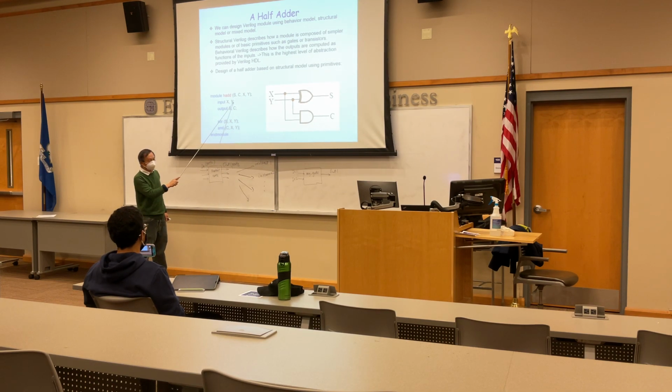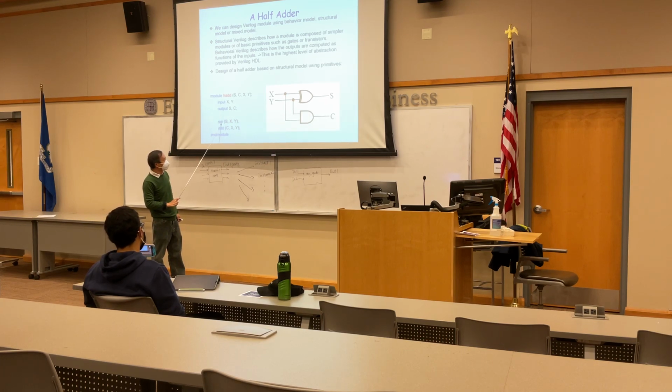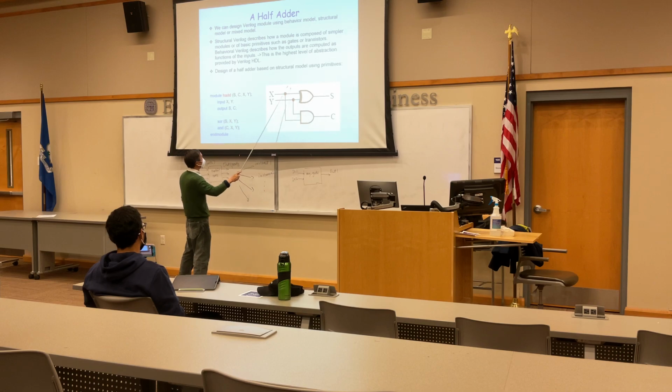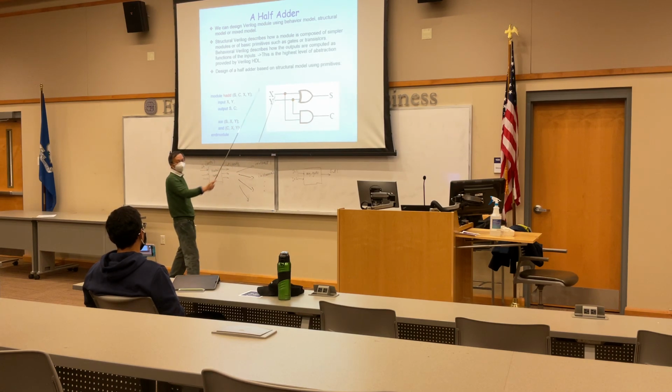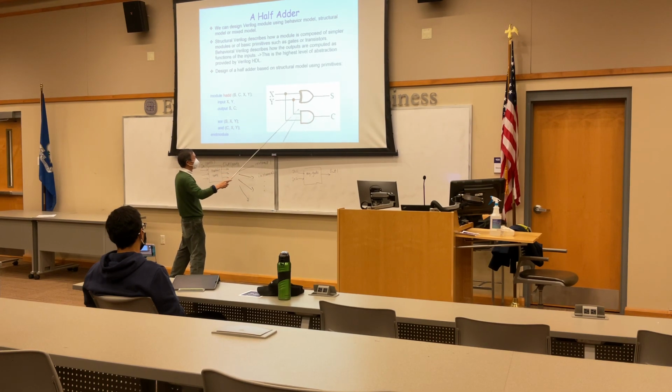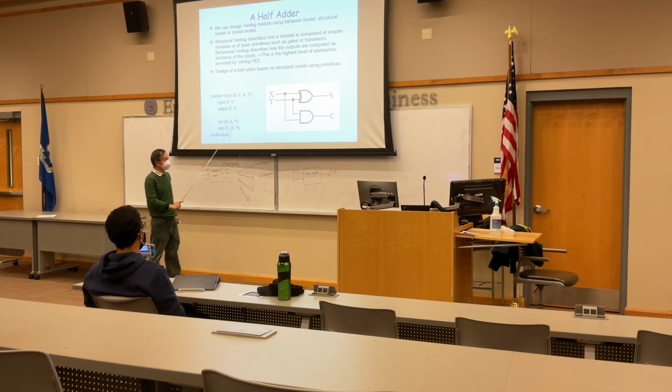And the inputs X and Y, because they are single bit, so we don't need to specify the bits. Output S, C. Now XOR primitive with S, X1, this input, and AND with this output, this input, X1. Done. Easy, right? Is it easy?